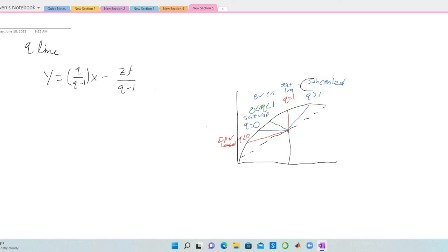If we have a saturated vapor, that means we're at a vapor at its dew point. As it comes in, it's going to increase the vapor flow rate up, but it's going to want to condense, so we don't have that drastic of a change. Initially that vapor is going to go up, so we're going to be spending more time in the rectifying section. And then if we have a superheated vapor, we're obviously going to be increasing the vapor flow rate up, but we are also going to vaporize some of our reflux that's coming back down and drastically increase that up, which means we're going to be spending a lot more time in the rectifying section.